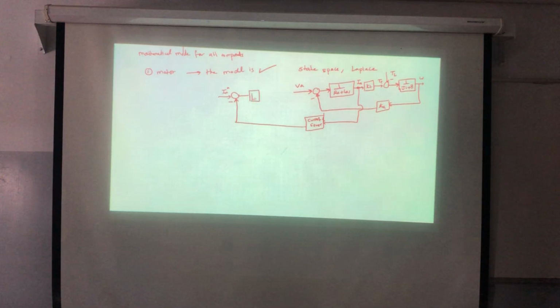Then this will go to a PI control, the current control. And the PI control will give me VC, the control signal. Now this VC, I need to find a mechanism to give it to the converter, because the converter will provide the voltage for the machine, correct?